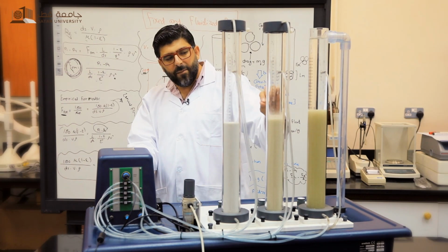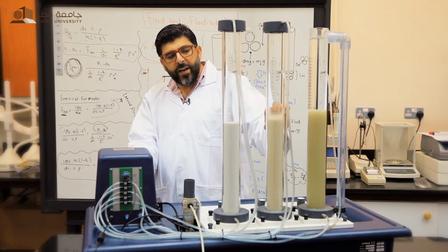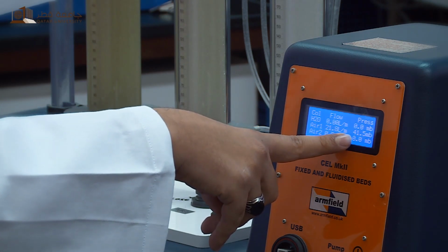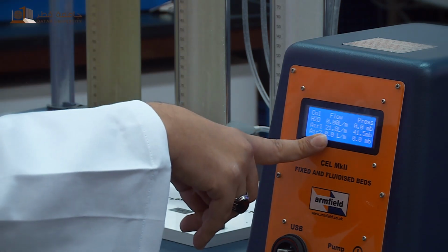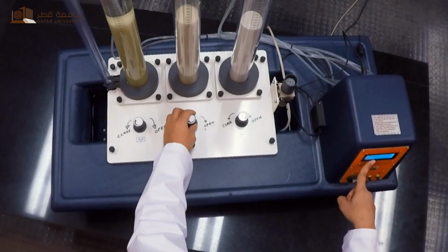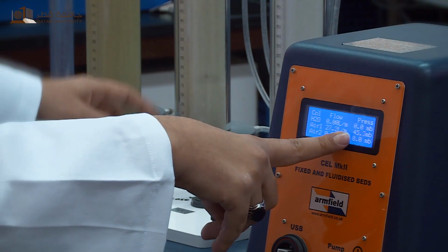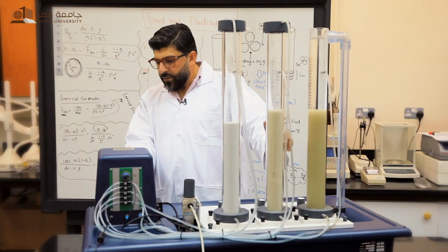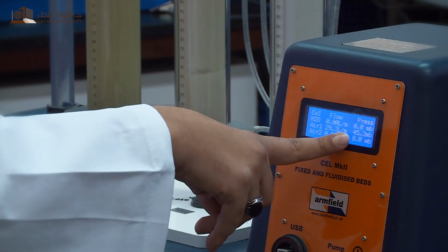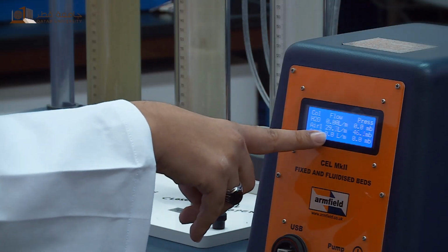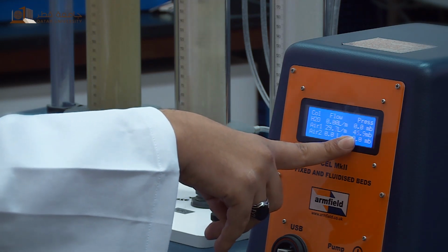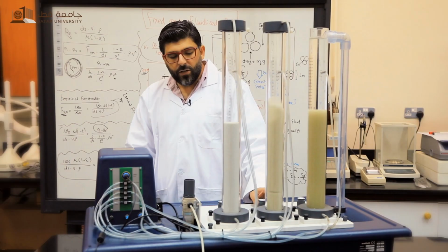You can see here some vibration of the surface starting. The pressure drop is 41.5. This is the flow. When we increase the flow rate again, now this is the bubbling fluidization. The pressure drop is around 45. When you increase the flow rate, the pressure drop stays constant. No more increase in the pressure drop.